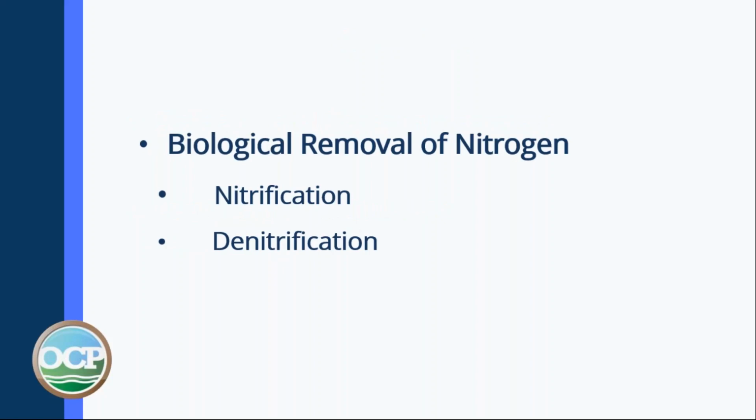Biological removal of nitrogen requires two steps. First step is a nitrification step, where the ammonia nitrogen is converted into nitrates, and then denitrification is where the nitrates are broken down into nitrogen gas and CO2.